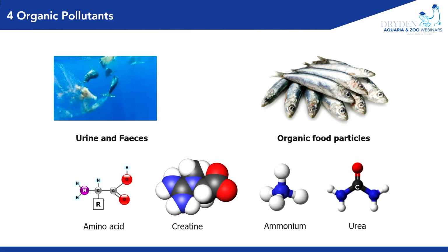If we can continually crop them out, and the more efficiently we can crop them out and get them out of the system, the higher our ORP will be. And that's even stable if we don't use ozone. So basically that means the less ozone we will need. And ultimately, we can actually keep a system clean. In many cases, with no ozone whatsoever, we can actually make the ORP go up. Or on the other side of that, your ozone might only kick in during feeding events, right? When it's needed, rather than operating all the time, 24 hours a day.